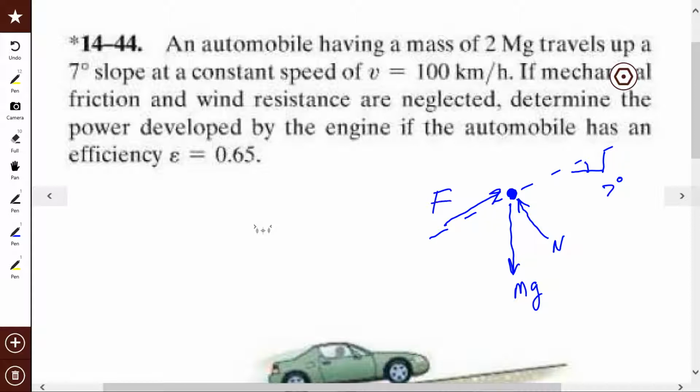So you're going to have a force like this. We'll call it F, coming from your engine. Ultimately it comes down to the friction on the road, right? And because you don't have any losses, I'm not losing any energy. You remember the bowling ball example that I gave you? Rolling friction is the deformations, right? In the case of a bowling ball, you're bending the wood underneath it. In the case of a wheelbarrow, you're pushing down the mud. That's why it's harder to push on mud than on concrete. Remember that? So this is kind of the same thing that's happening here.